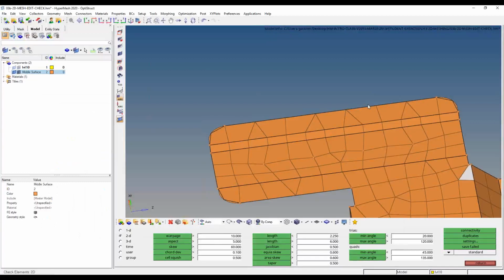Your mesh is sort of the opposite. Your mesh is only as good as its worst element. Doesn't matter if 99.99% of your mesh rocks. If you have one really screwed up element, some solvers will literally not solve it, and they'll say, this mesh sucks. You have an element that totally failed my internal quality requirement. So a better way to think of this is that your mesh is only as good as its worst quality element.